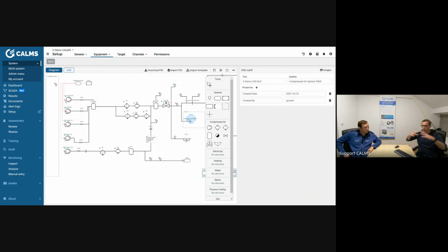So we will collect all the data on the same server, on the same graph. And we will play a little bit. We will ask you to open the valve, to close this compressor number 5 that you have here, to see how it operates, and we will test each compressor. What is the contribution, which one is the culprit? We'll find it.